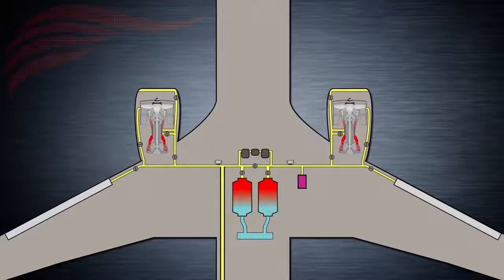The following systems and interfaces are linked to the right side of the pneumatic manifold: Engine 2 bleed air system, Engine 2 start system, ground pneumatic connector, right air conditioning system, right wing anti-ice system, hydraulic systems B and standby reservoir pressurization, and isolation valve.